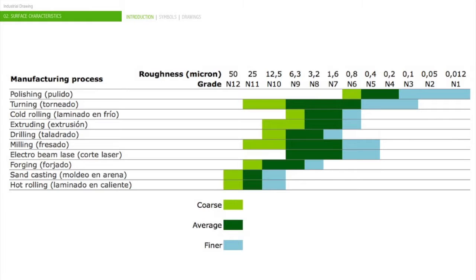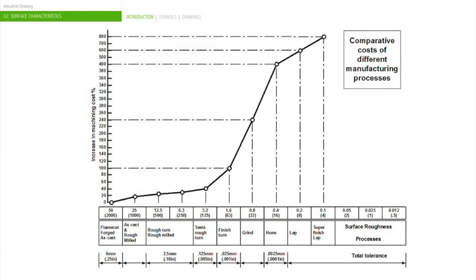Different manufacturing processes yield different amounts of roughness on the surface. Basically, the finer the finish and the tighter the tolerance, the greater the cost. Ideally, from a cost-impact point of view, it is best for the designer to accept the finish and tolerance capability of the primary process.